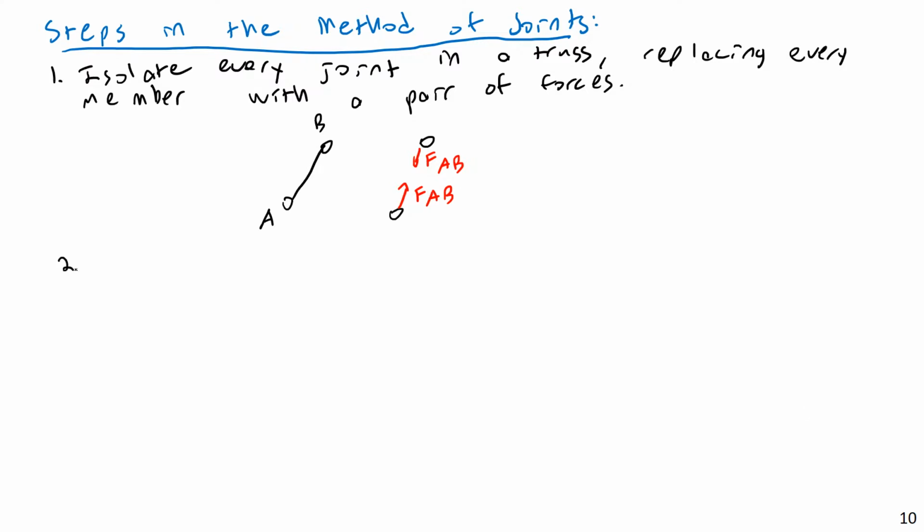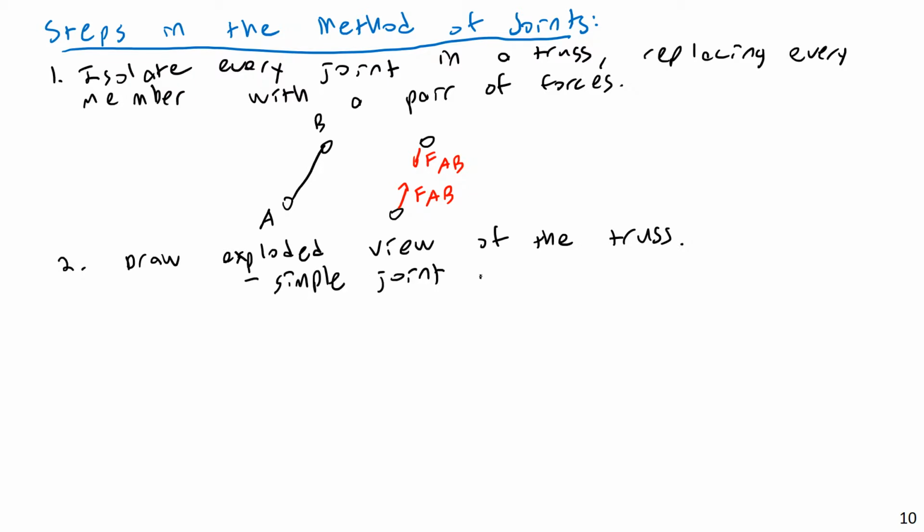Two, draw what I refer to as the exploded view of the truss. Draw the exploded view. And the exploded view should show just simple labels for the joints, but then also labels for all member forces and external reactions.